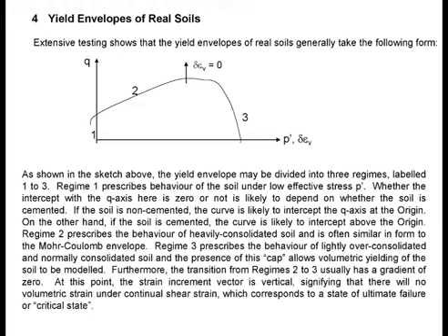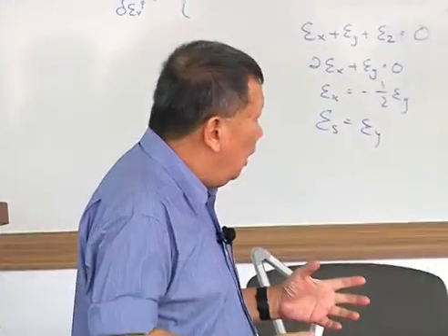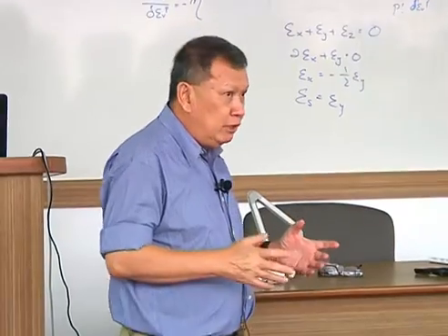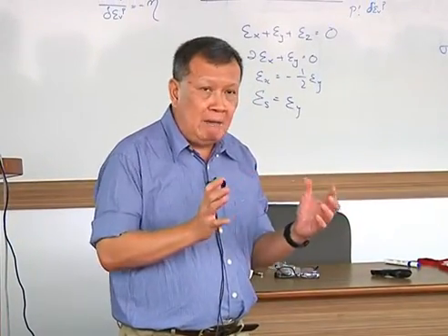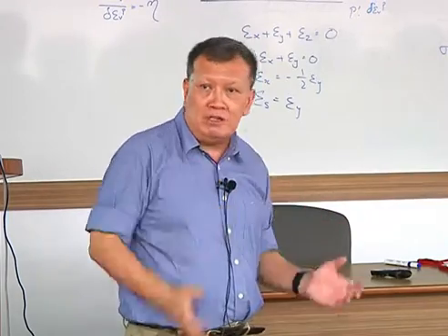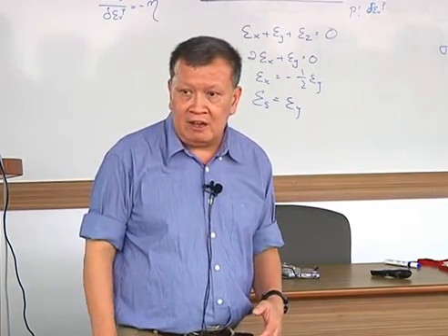And this is the shortcoming of the Mohr-Coulomb, which is related to the method A that we have seen before, and which is also related to the fact that the Mohr-Coulomb is unable to model compression. So this is essentially all related. So when we go on to the next part, starting tomorrow morning, I will be talking about critical state soil mechanics, leading you into Cam-clay as a basic example of how a model with a compression cap can be defined.